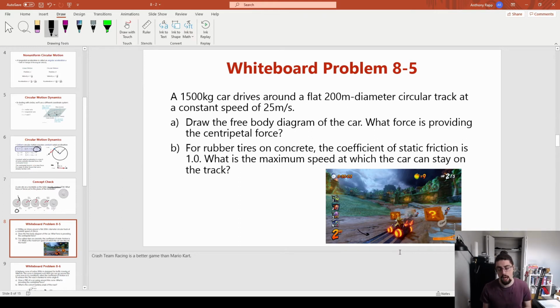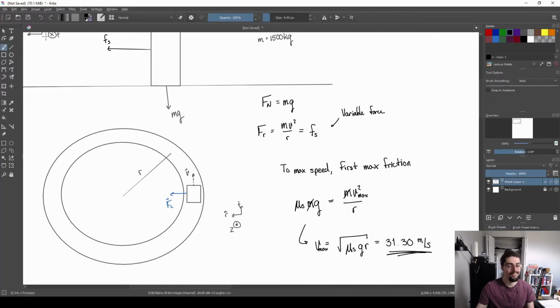But yeah, different types of tires will be set up in different ways depending on what you're going to be using. Like drag tires, for example, are a little bit more low pressure and they've got a lot more flexible rubber because it tries to layer up. If you ever see a drag race in slow motion, with the actual drag cars, it's really incredible because they'll fold up in a bunch of different ways and you'll maximize that surface area with the ground. It becomes non-circular at the very start of the race. It's pretty cool.